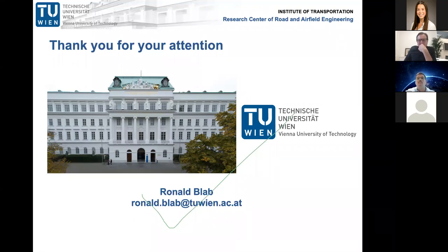It made sense for us because you can easily calculate the creep compliance from the DSR test, so from the shear modulus, and transform it in a very easy way in this upscaling scheme where we upscale the viscoelastic properties. And here we had existing solutions for how to transform the time space for the creep compliance to the Laplace-Carlson space and to back transform it with the so-called Stehfest algorithm. I explained it a little bit to you. I think that was mainly the reason why we chose the creep compliance, because we had existing solutions for this transformation.